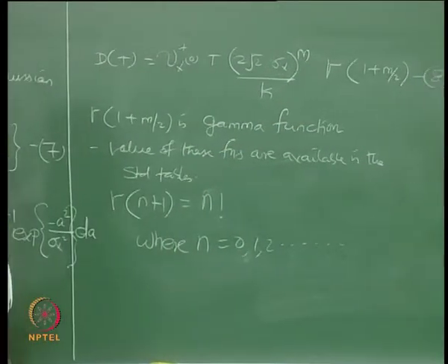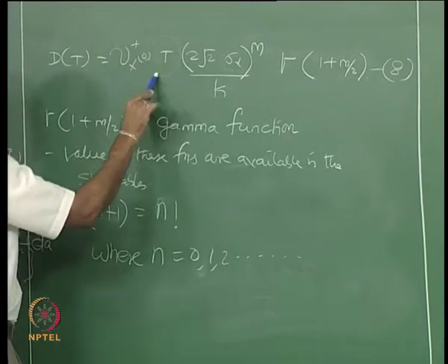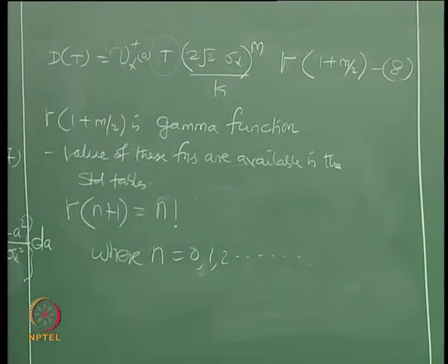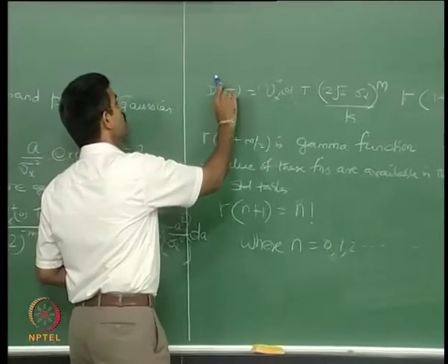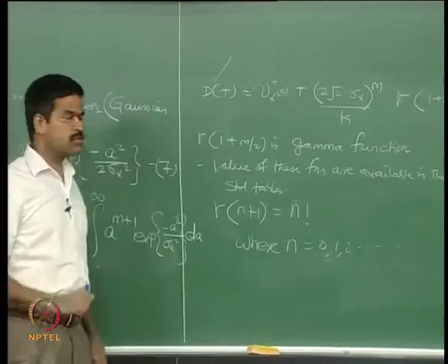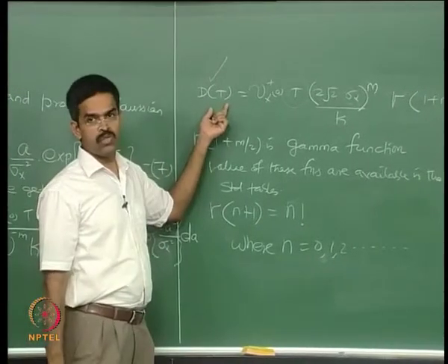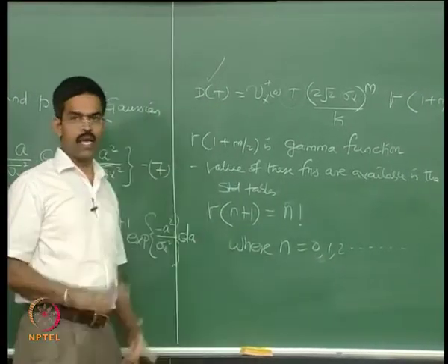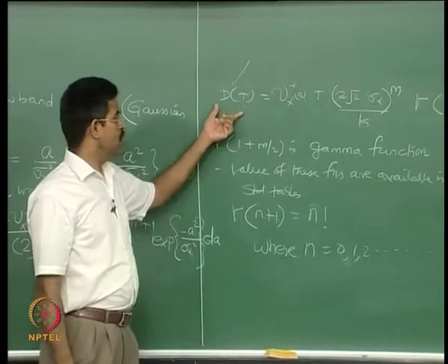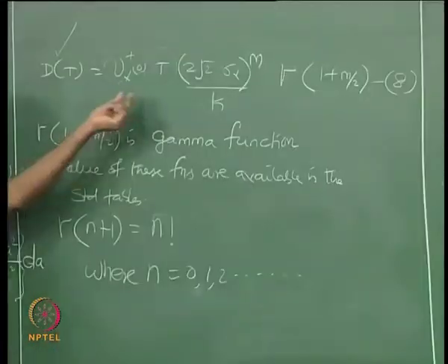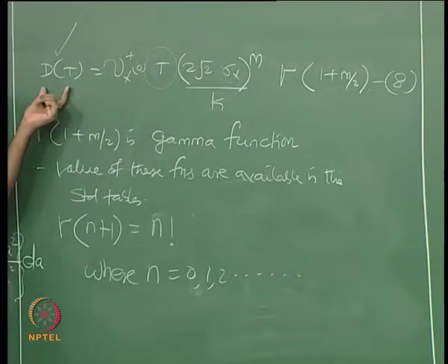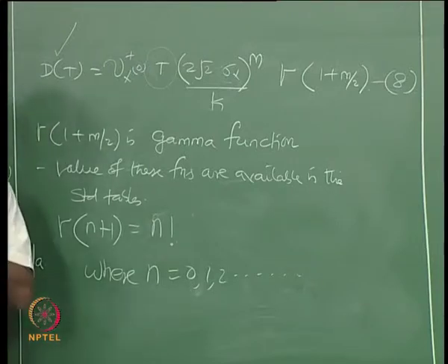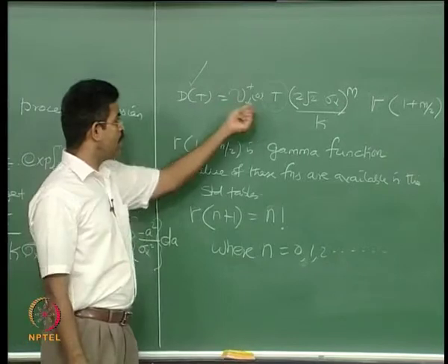Now, in this equation I get the value of t, which is nothing but the lifetime estimate of the structure based on the cumulative damage caused because of exceedance of stress values in a stress range of 2A. So, it is a fatigue damage. I am interested in finding the life estimate of the structure based on the cumulative damage caused by stress exceedance beyond a threshold value in the range 2A in a period t.